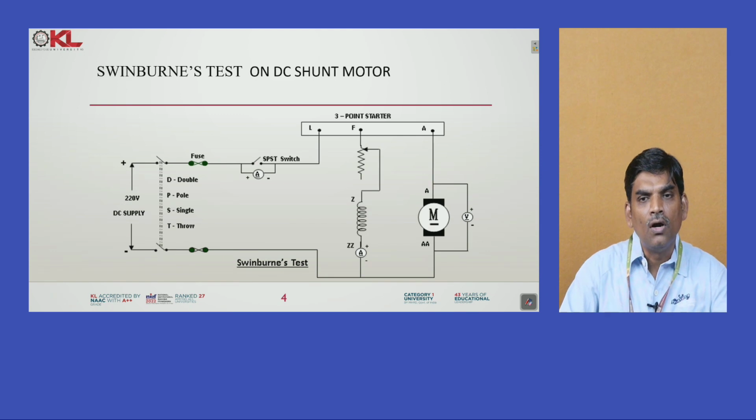Suppose it works as a motor, how efficiency is obtained in different load conditions, and suppose it acts as a generator, how the efficiency is obtained in different load conditions. We analyze this in this test. By using this test data, we analyze it as a motor and as a generator also.